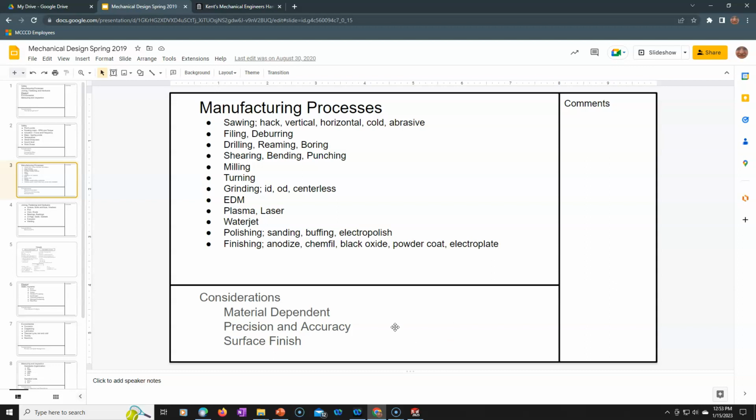The precision and accuracy, if we know that we're going to be doing grinding, then our milling and drilling processes have to leave enough material that after it's hardened, after we've done those processes, the grinding and the finish machining will have enough material to remove. In the case of anodized, it builds up a little bit, black oxide not so much.